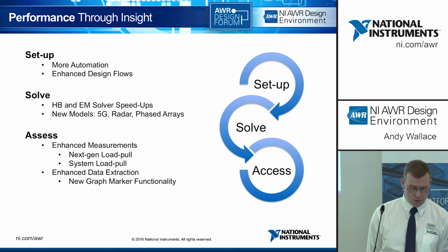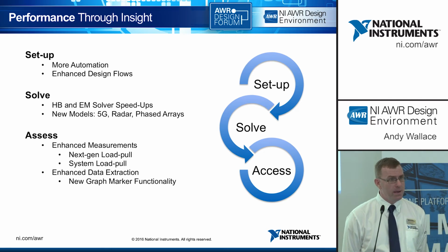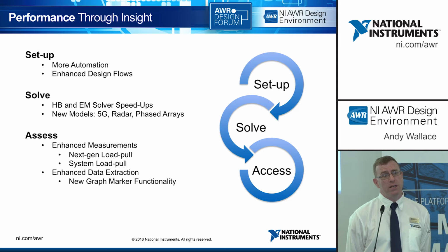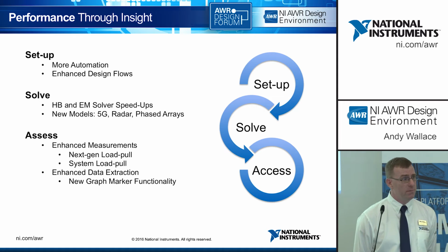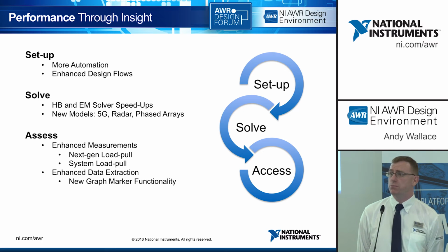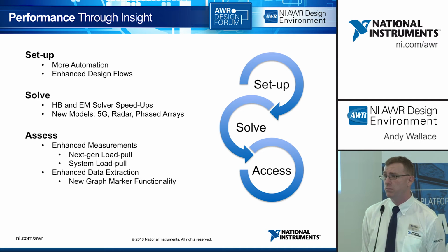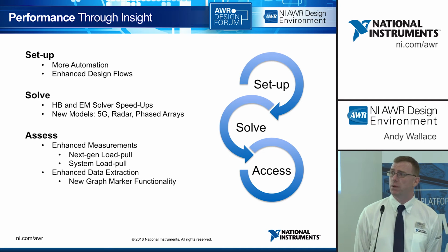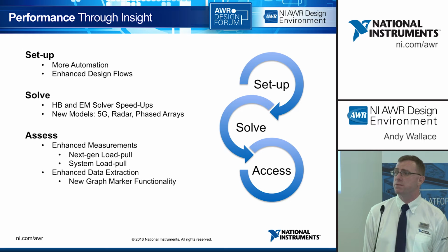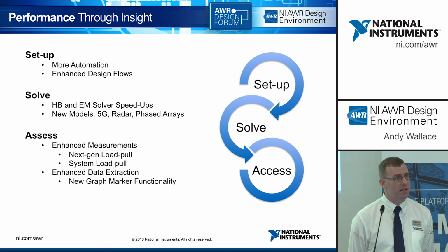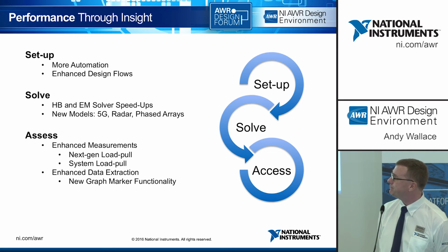And I've mentioned the new models in the systems tool. In particular, we've done a fair bit of work looking at antenna arrays, particularly phased array antennas. We can simulate those with in situ measurements, so a circuit level signal producing a 3D antenna plot, and those antenna radiation plots can then be used in the system tool as a measurement data file. So we can look at different directions of the phased array antenna, a signal perhaps on boresight, maybe a jam signal off boresight.